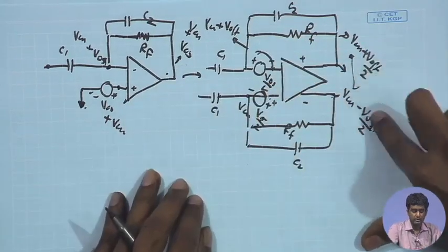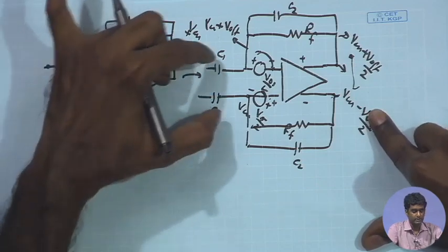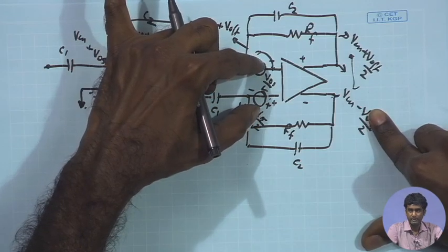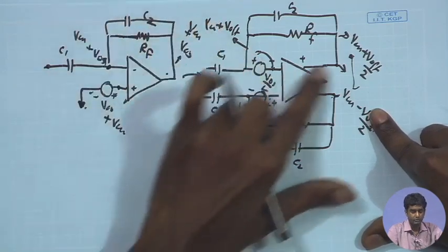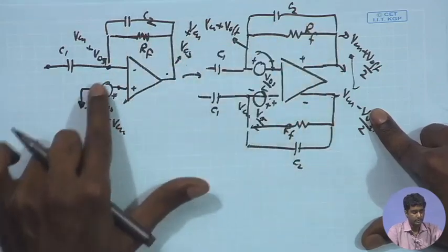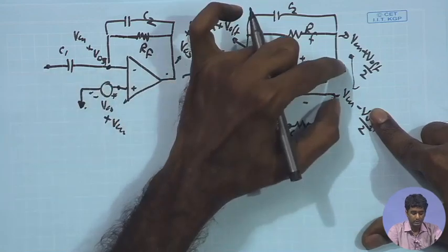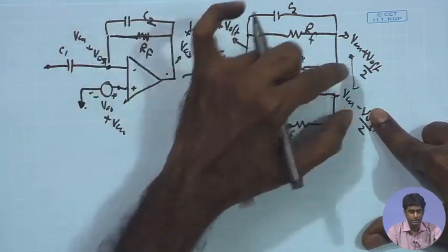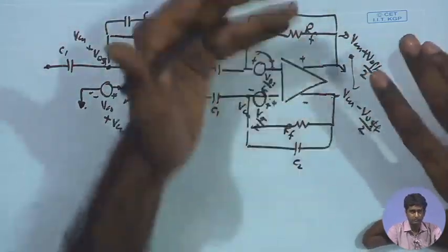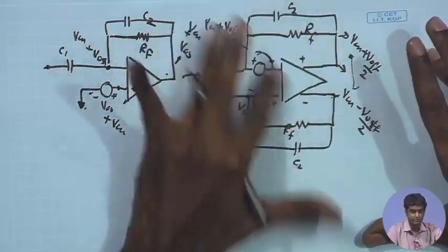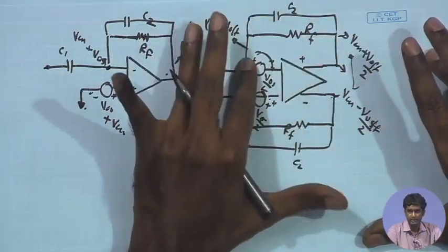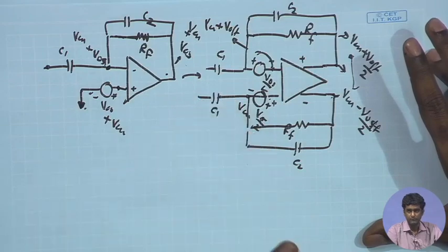So, you have the difference just given by the V offset, corresponding to the effective input referred offset of the amplifier. In case of resistive feedback, the difference between the outputs is just equal to the offset voltage, and therefore it is not magnifying that offset and saturating the amplifier. So, this resistive feedback in fact is helping us in taking care of the offset also.